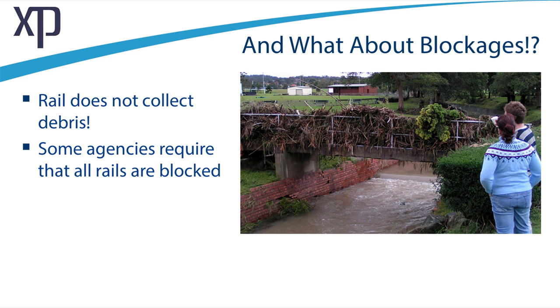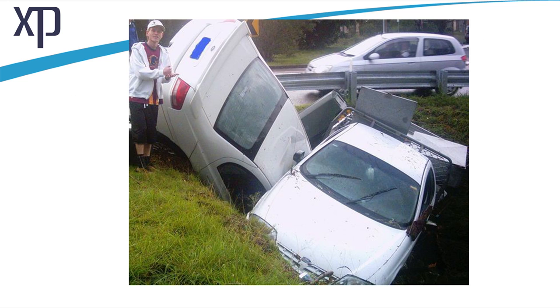And blockages. I'm not sure about elsewhere in the world, but here in Australia, this type of handrail is actually recommended as it doesn't collect debris. But whether that actually works in reality has been proven not to be the case. And so a lot of agencies these days are very much specifying that rails are modelled blocked or partially blocked. And to do that, we can use our layered flow constrictions if you're using the 2D approach. And we're still working on how to model these cars. That's probably a feature for an upcoming release.